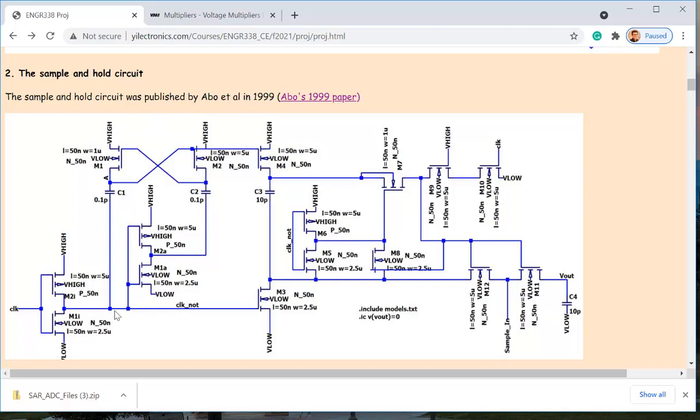So that's why you need a higher voltage. And this part of the circuit is a charge pump. It's going to provide a higher voltage, in a similar way as the one I just saw, the voltage doubler, okay? Use the cap. And the cap, the charges here have no place to escape. It's going to accumulate over there. So it's getting a high voltage to this point.